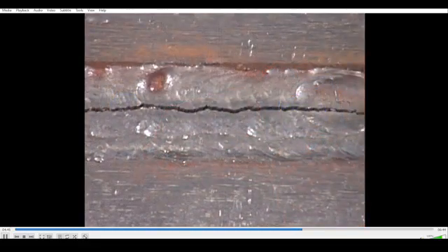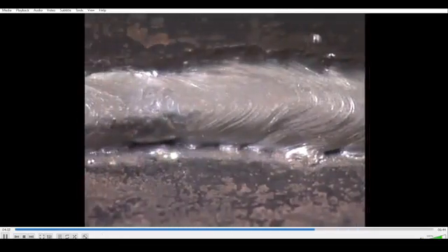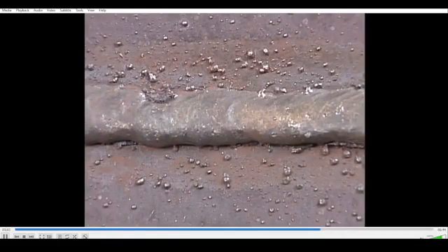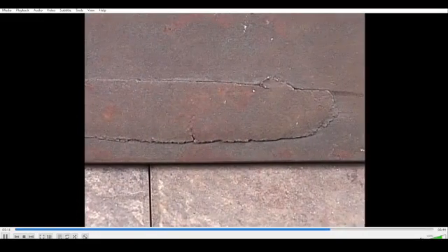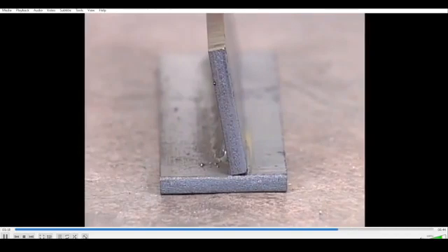Examination of the weld surface itself is another part of post-weld inspection. Common discontinuities visible to the surface could be cracks, porosity, undercut, overlap, arc strikes, and excessive spatter, to name a few. Each of these will have detailed allowable limits based on codes or inspection procedures. After welding examination may also reveal base metal defects, such as delaminations, cracking, or excessive distortion, all of which should be clearly marked for repair.